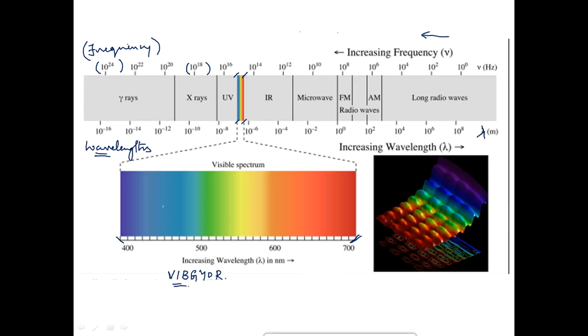Now the point is, if we fabricate a light emitting diode, then we'll have to tune the band gap during the fabrication stage itself, so that the emitted light will fall under some of the color ranges. Two types of LEDs are very popular. The first one is visible LEDs, which emit colors that can be seen by the human eye.